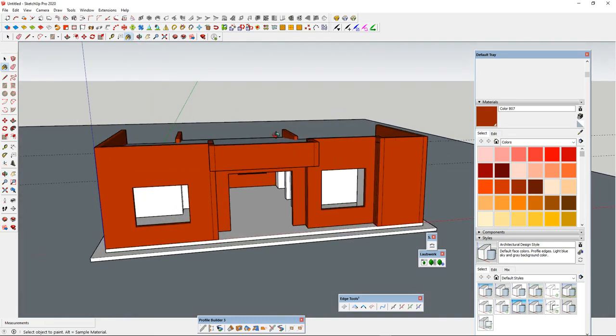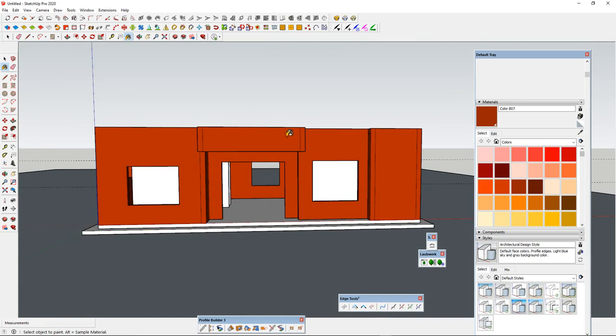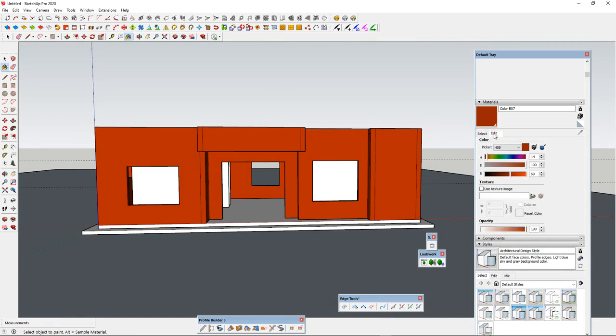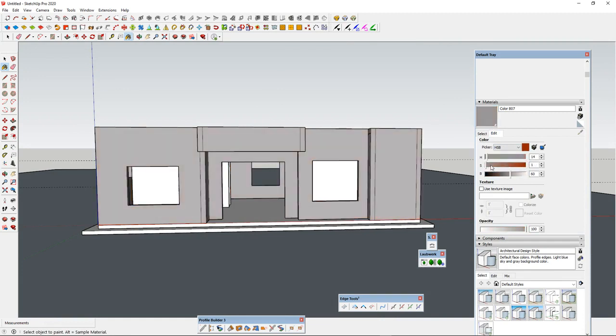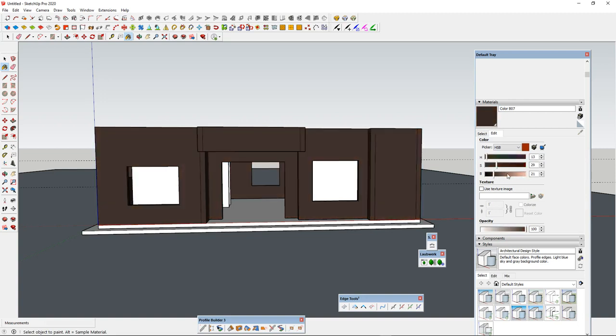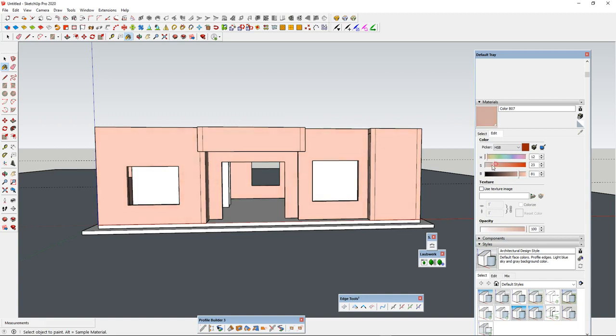And these same colors can also be edited by going to this tab, where you can fine tune how bright or how saturated that color is. If you're within the edit mode in HSB, H means hue, the color, S means saturation, how strong or dull the color is, and B means how bright or dark the color is. This is something you can use to fine tune the colors that you're using within the model.